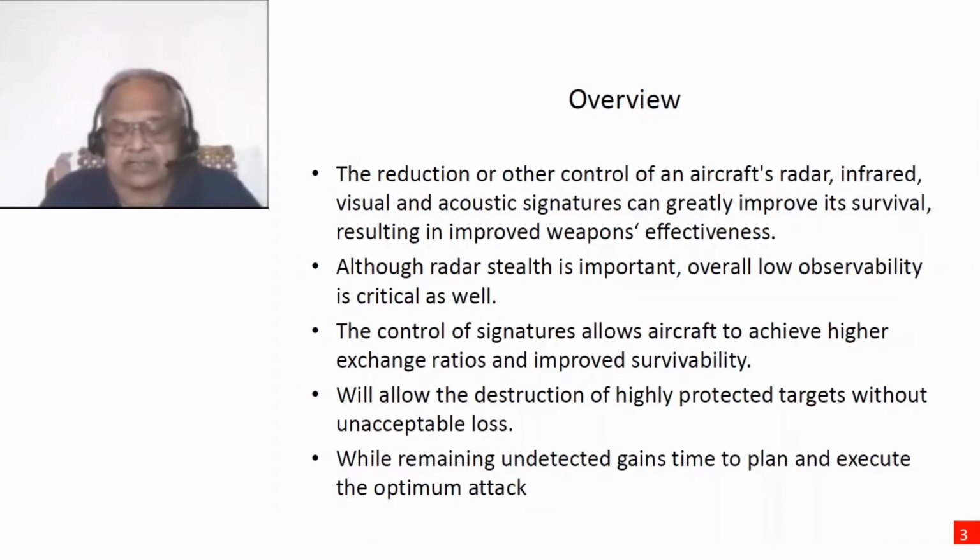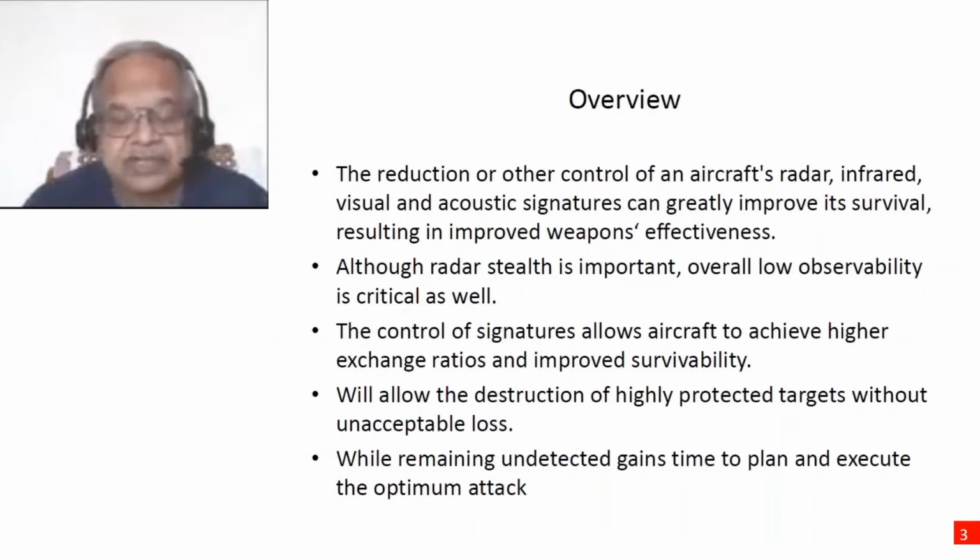And the loss in terms of the aircraft being shot down is also minimized. While remaining undetected gains time to plan and execute the optimum attack. So that's the whole idea of reducing. You cannot, of course, eliminate and become completely invisible. That's a fairy tale. All you can do is reduce your signatures.